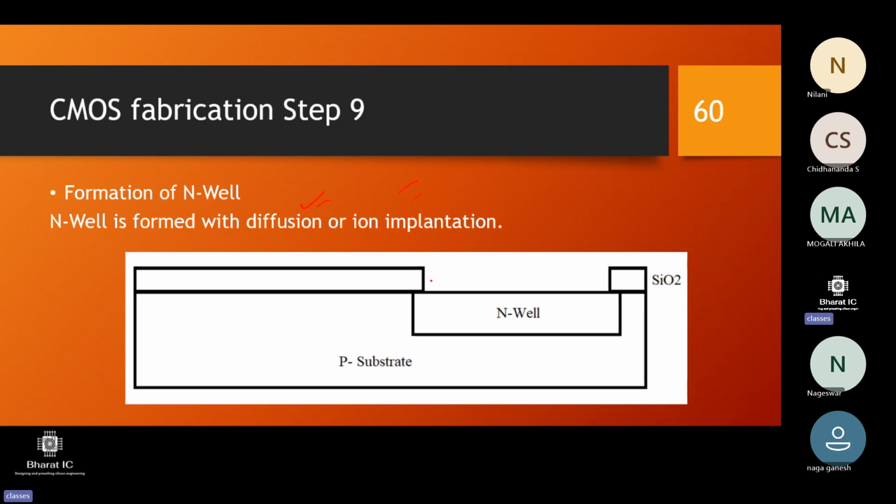With the ion implantation, the diffusion has been formed over this one. The N-well is now formed over this trench part. Over this trench part, the N-well triangular structure has been formed on the substrate. Okay. Now, up till here, the N-well is created. You can see how it has been done.